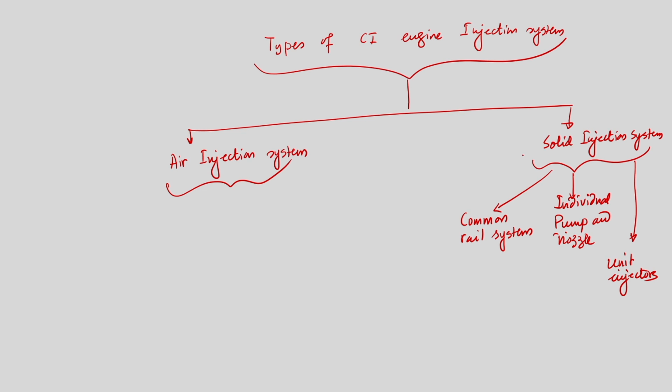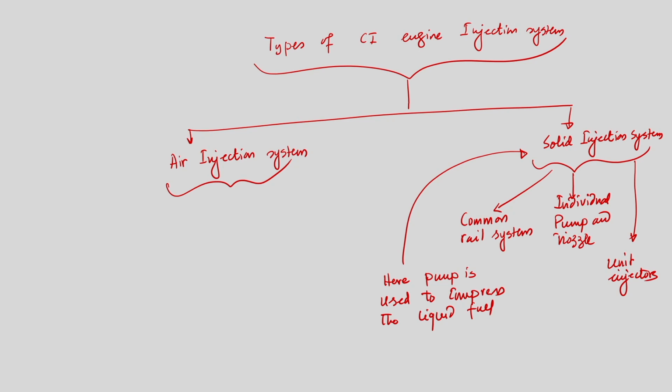For the solid injection system, a pump is used to compress the liquid fuel, but the air injection system will be using compressed air to sweep the liquid fuel which will be injected into the engine.